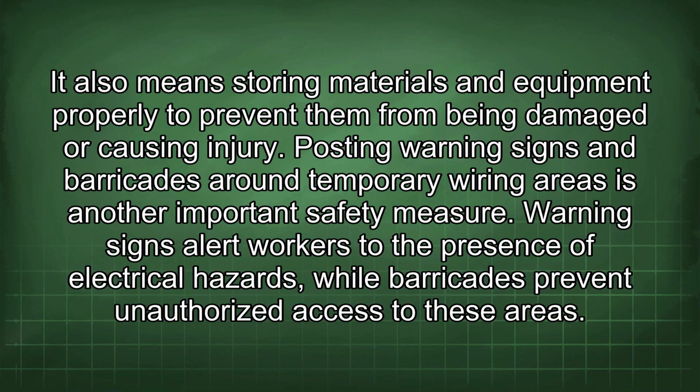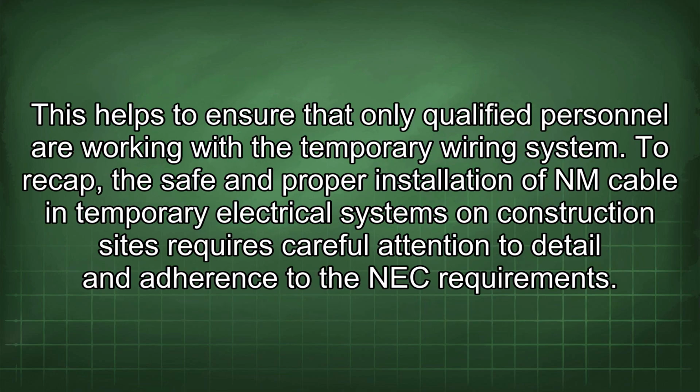Posting warning signs and barricades around temporary wiring areas is another important safety measure. Warning signs alert workers to the presence of electrical hazards, while barricades prevent unauthorized access to these areas. This helps to ensure that only qualified personnel are working with the temporary wiring system.